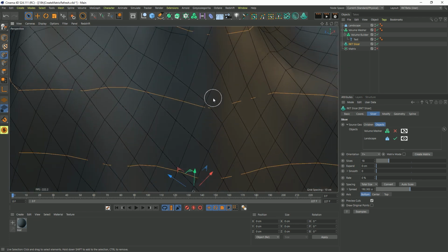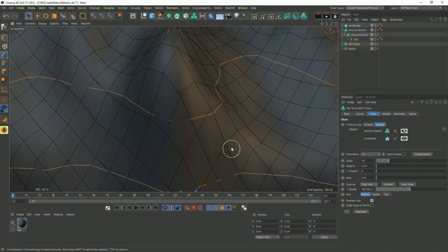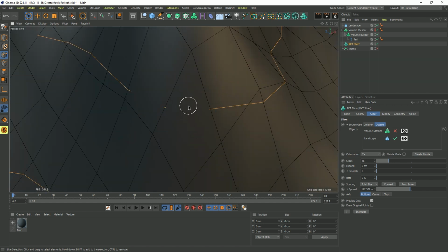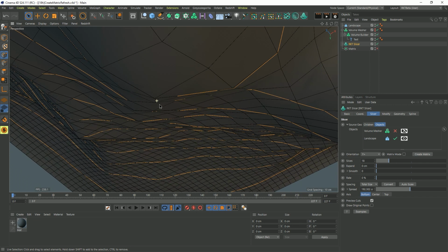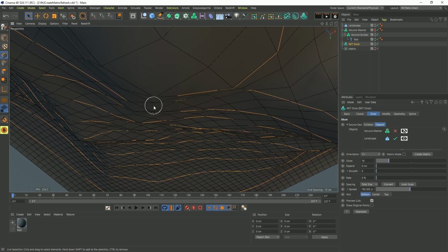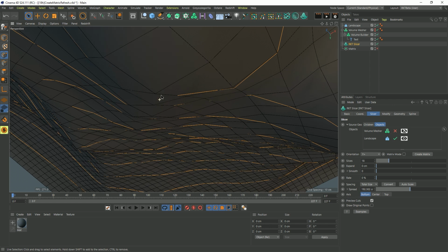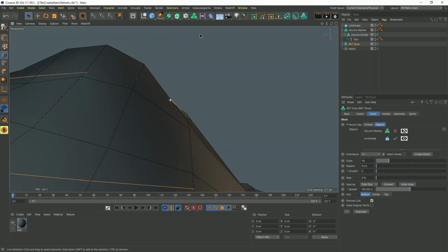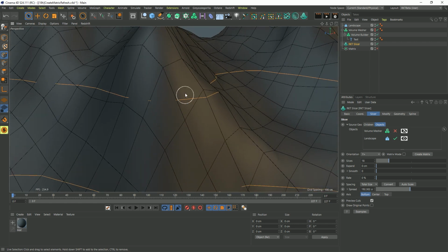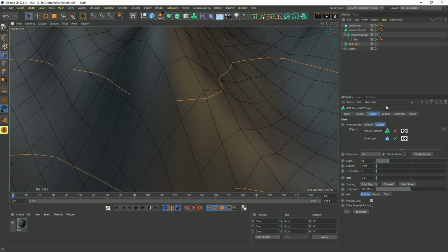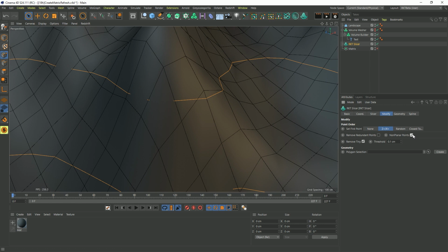Well, that's because a lot of models that you're working with are not going to be planar, meaning the individual polygons are not necessarily perfectly flat polygons. So let's find a rough one, like right here. You see we've got this polygon. If I spin the camera in a really extreme way, you can see that this one polygon definitely isn't flat. It goes up, down, over, up, down, over. So it's almost like it's two triangles, and those have additional dimension to them. So those are not being currently acknowledged by the slicer, but they can be just by turning on non-planar points.